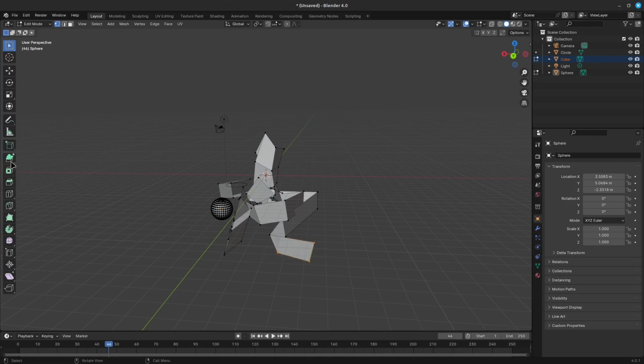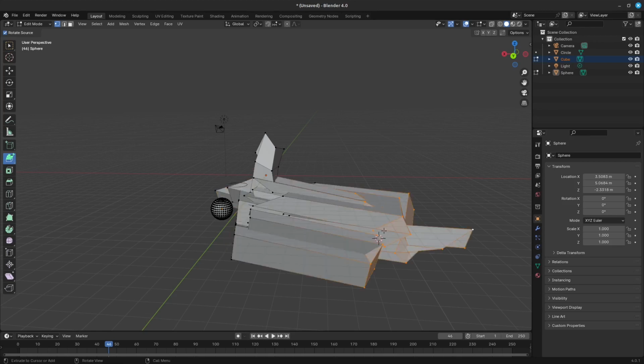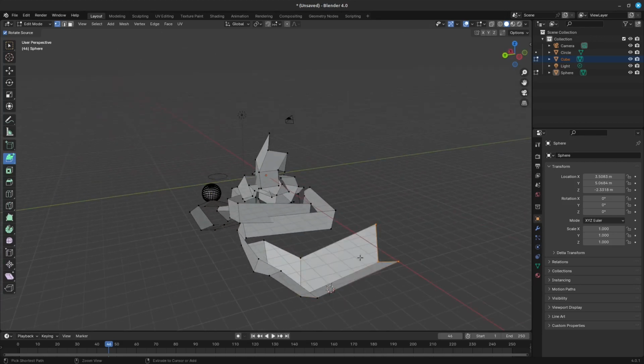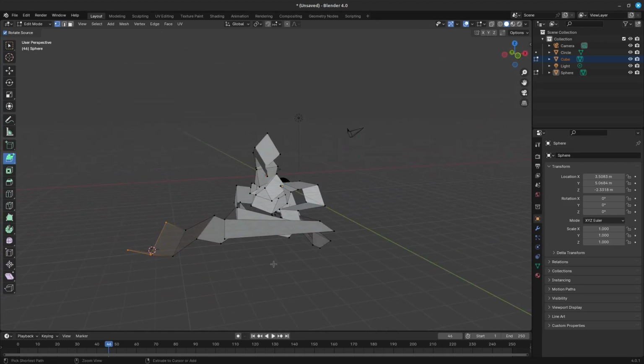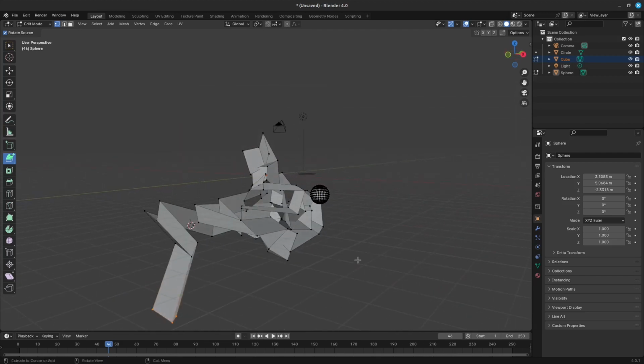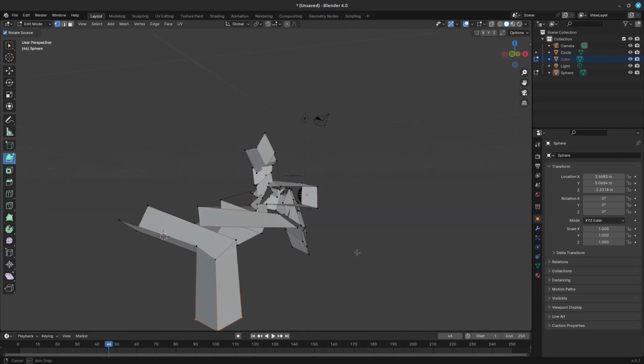When adding objects with Control plus the right mouse button, the extrusions of the selected elements, being vertices, edges, and faces with the Control plus the right mouse button, are viewport dependent. This means once you change your viewport, for example, from top to left, bottom, or right, the extrusion direction will also follow your viewport and align the extrusions with your planar view.